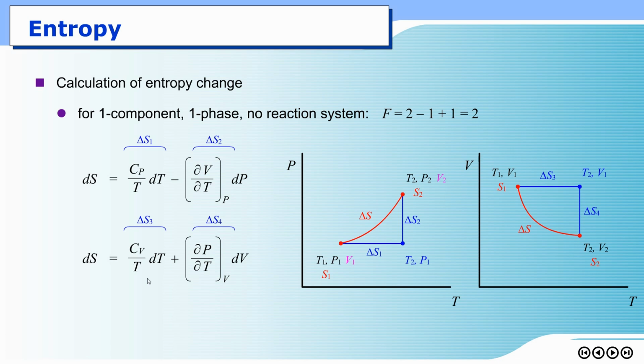But some of you may ask, can we use the relationship between Cp and Cv, just like Cp equals Cv plus R, and change from Cv to Cp or Cp to Cv accordingly? The answer is yes, you can under certain criteria. For instance, Cp equals Cv plus R is applicable only for an ideal gas. If your system is not an ideal gas, then they are related in a different manner that you may or may not know. Then the conversion from Cp to Cv for a non-ideal gas may be so difficult that picking up the data of Cv is easier than converting from Cp, for instance. So the former choice depends on the data that you have in your hands.